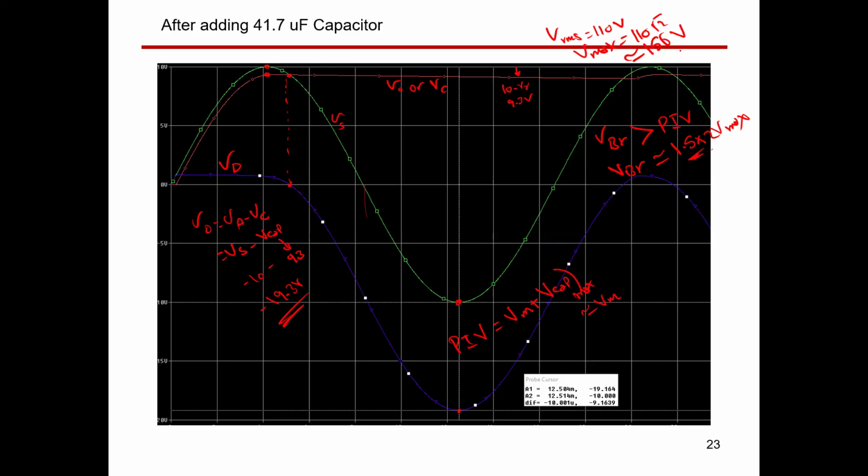Okay, guys? So this is how we can apply a safety factor and select the capacitor. The same is also true for the diode. Since the peak volt of the supply is 156, 2V maximum will be, in this case, 311 volt. So use a diode with at least 400 or 500 volt. You may not find 400, you may find 450 volt.